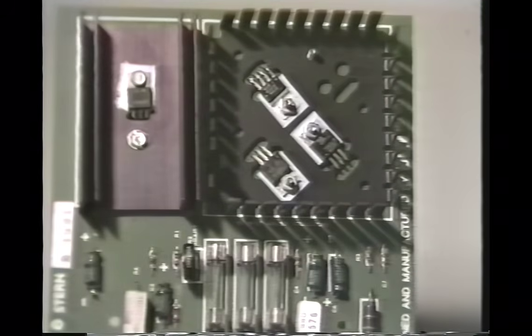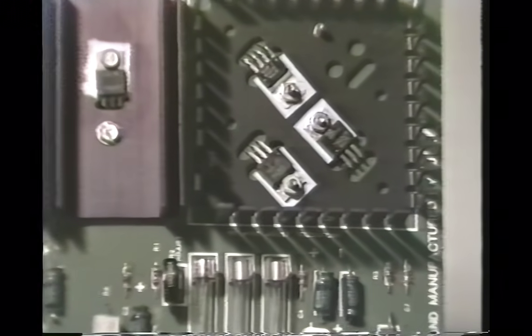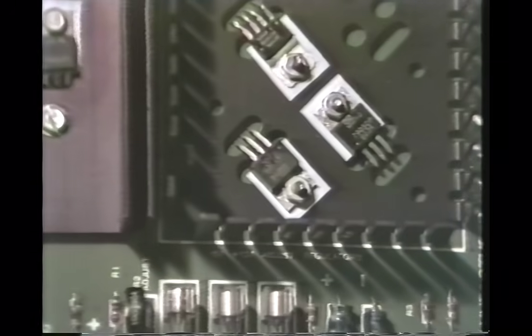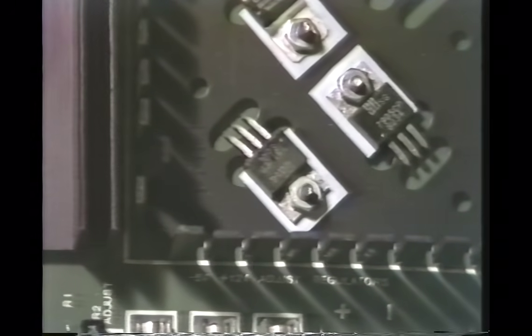There's another type of regulator that you'll often see used in place of the 78 series regulators. And these are the LM340T series. As before, the voltage is indicated by the number following the T. Thus, the LM340T-5 is a plus 5 volt regulator, and so on. Both parts are interchangeable, and you may even see a single device with both the 78 series and the LM340 series number printed right on it. This Stern power supply is typical of most that use 3-terminal regulators, and here we see 3 regulators mounted to this black aluminum heat sink.